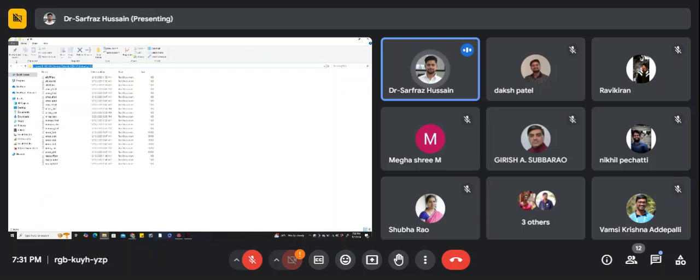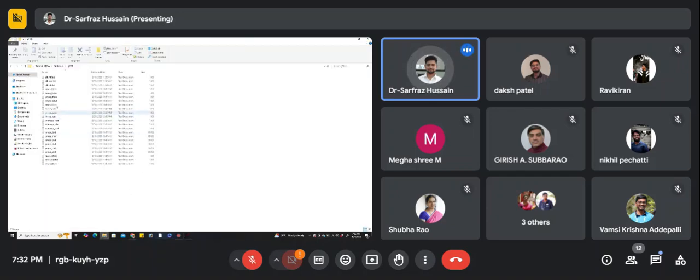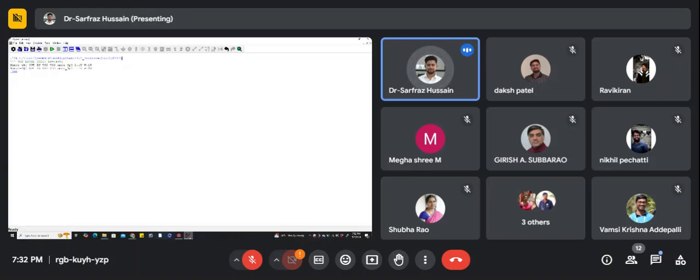So let's call upon .lib, and we give the library location as this, then slash, and after that the file name that we are including. In this case we are including this CMOS underscore TT dot txt. So this file we are calling upon, and here we have included this particular file. Now when we include this file, these two models will be included.